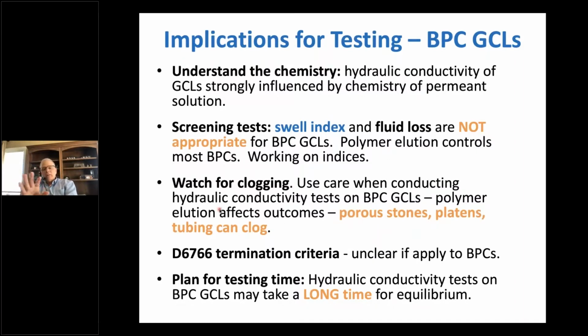Watch for clogging. Pay attention to polymer clogging pore stones, platens, tubings. All those different pore spaces can get plugged with polymer. Flush the outflow regularly. Observe the outflow. Look for potential clogging. Do not use pore stones. I would avoid them if you can. I would use a nice, heavy, non-woven needle punch geotextile.